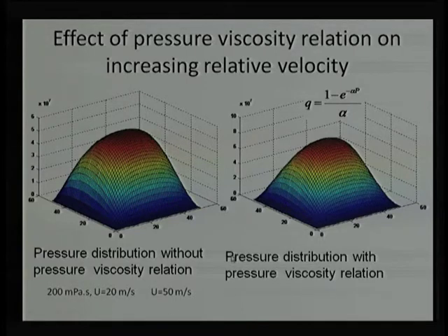Here we are saying that viscosity we have maintained 200 millipascal second. Initially velocity was 20 meter per second. Now, velocity has been increased by 2.5 times, so it is turning out to be 50 meter per second. Of course, in these situations we have not accounted for change in geometry due to pressure.